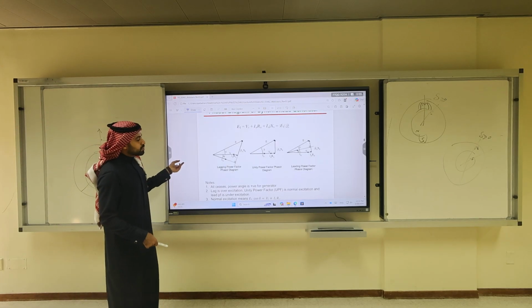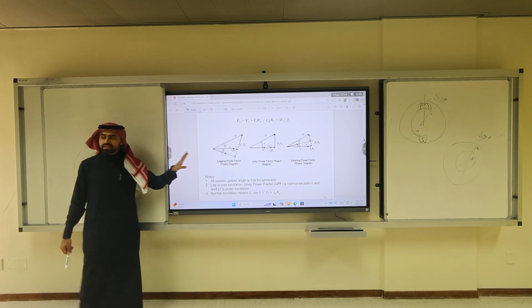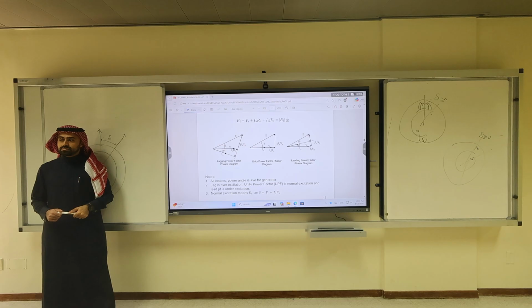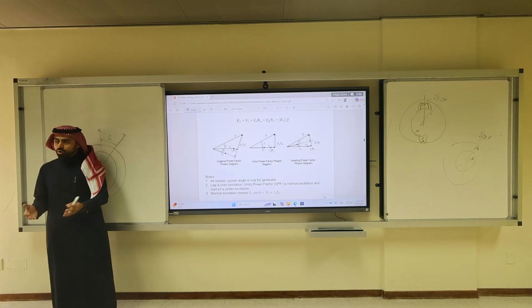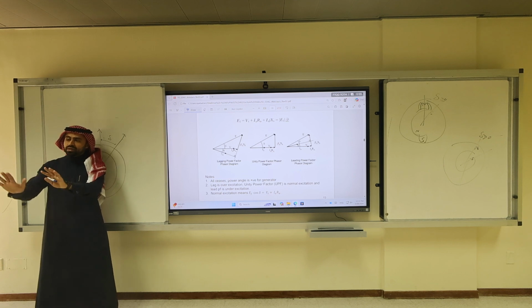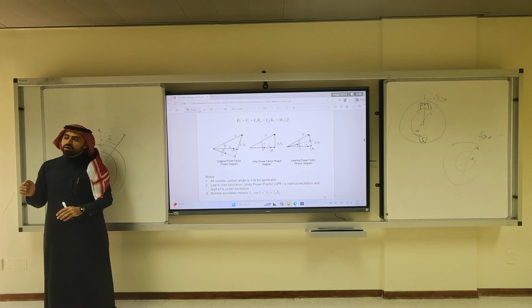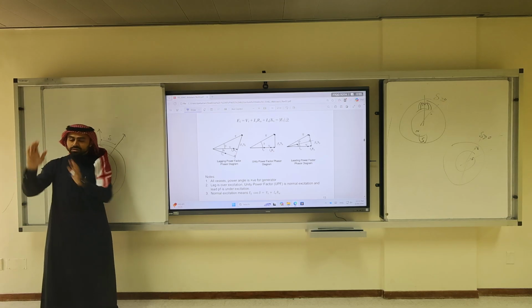Let's continue. How to read these phasor diagrams? Yes? So we don't aim to make delta 0. Right? No. Delta is the torque angle. It has to do with the synchronization of your synchronous generator. Of course it has to do with the torque, and many other things. Even the loading conditions would change delta. If you add bigger loads, delta will change.